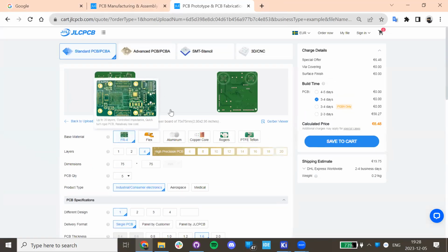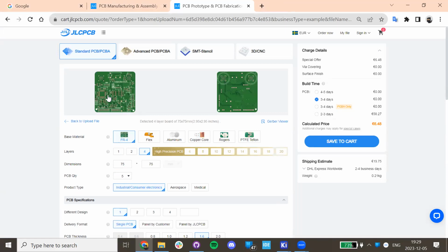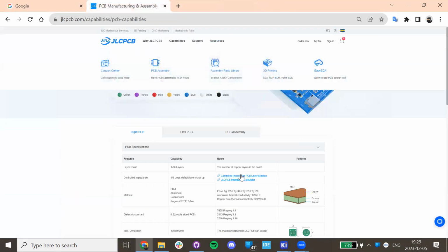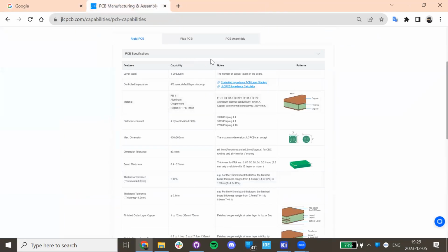But some things you have already specified, like the sizes of holes and where things are placed, and they cannot make just anything. So you should follow these guidelines, and if we are doing a rigid PCB, not a flex, you should always try to be a bit on the safe side of these capabilities, because the safer you are, usually it's cheaper, and the risk of a manufacturing error occurring is less.